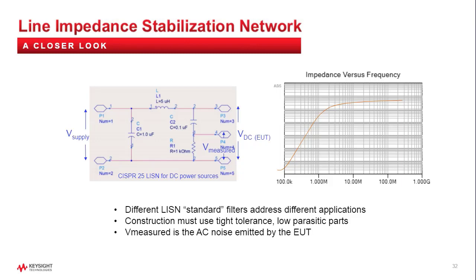These are purchased parts. I think the confusion is that it's a high pass between the switching circuit and the spectrum analyzer. But it's a low pass between the switching circuit and the mains. You have to specify from what to what. I think that's the confusion. So it depends on which terminal you're talking about. Is it the input to the output, or the output to the spectrum analyzer? Yeah, you're exactly right. It's a high pass to the spec in.